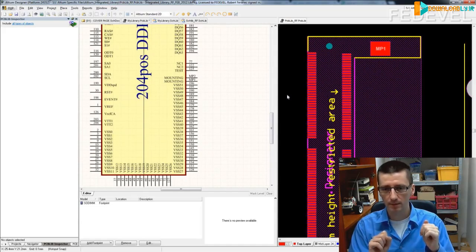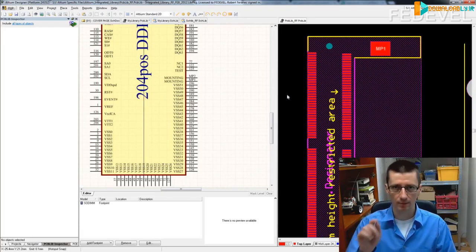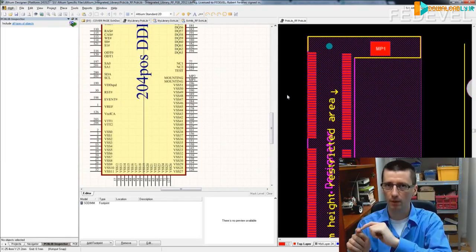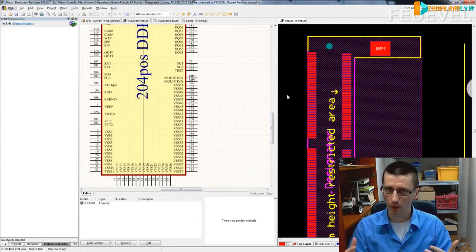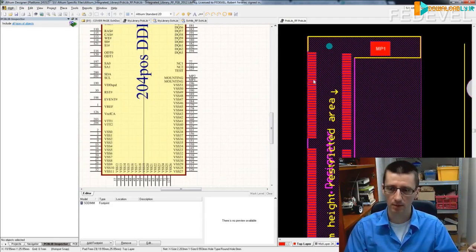And what happened is it was not correct, because pins in the schematic were like 1, 2, 3, 4, and pins in the footprint were like 1, 2, 3, 4, but differently arranged. So it was wrong. Always be sure pins in the schematics are exactly like pins in the datasheet, and pins in your footprint are exactly the same as in your datasheet. Many mistakes happen like this.